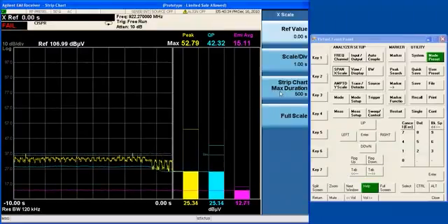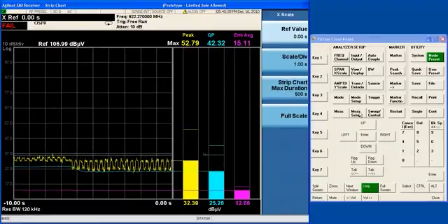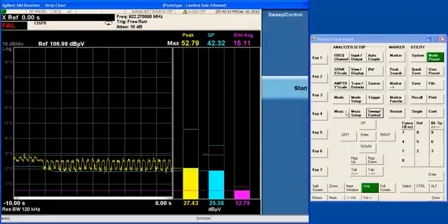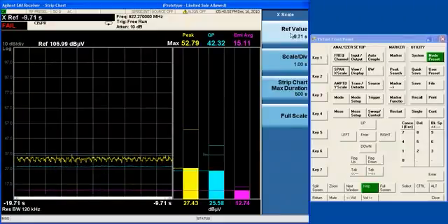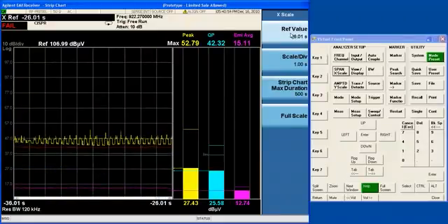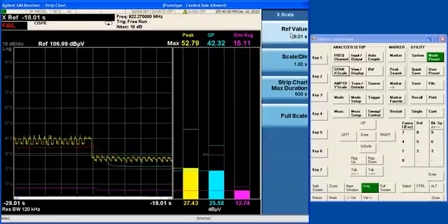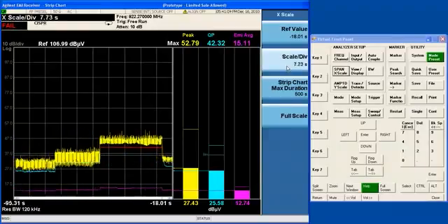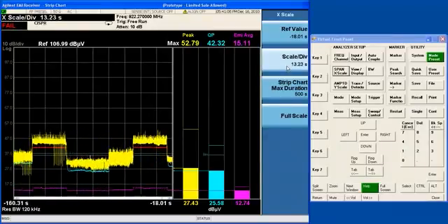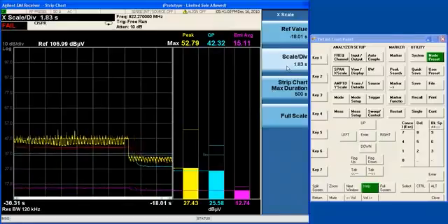And I can actually look at all of the data that I've captured for that whole 500 seconds. So if I stop the meter display and then adjust the reference values, say, it'll basically let me scroll through the display, and I can look at the past data that's been captured already. And if I adjust the scale per division, I can compress or expand the data and see basically everything that I've already captured. I can use markers in this display.